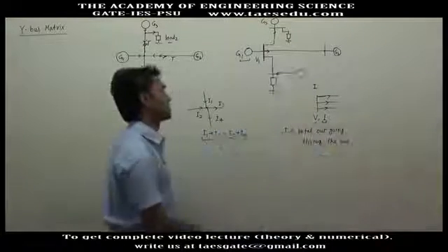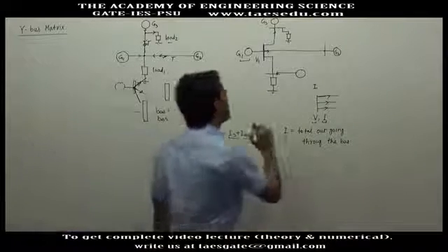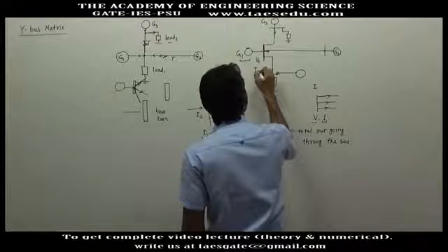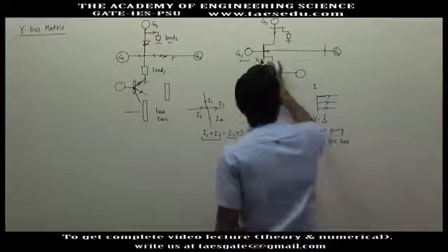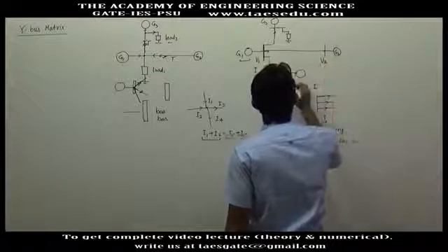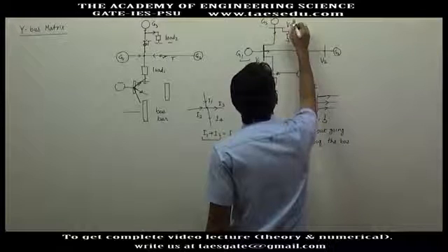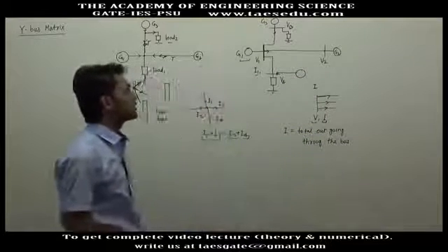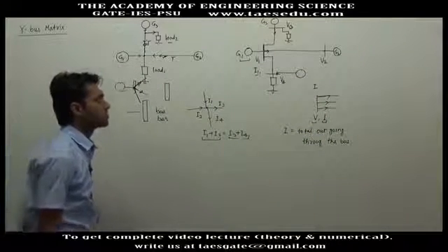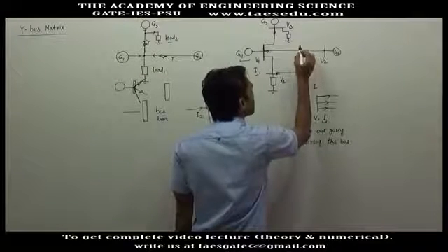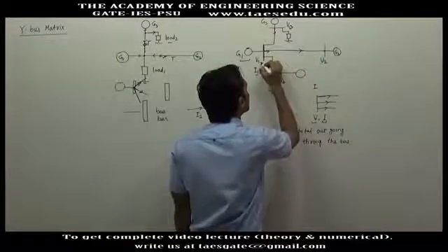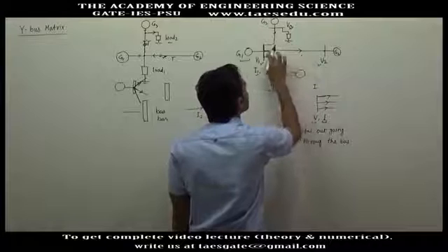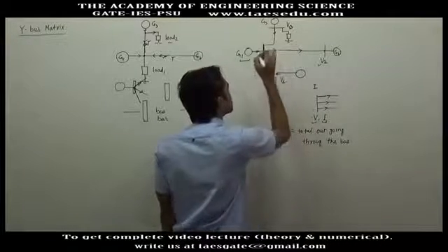Okay, this will be the current of a bus. So this current through any bus, let's say this is bus 1, I will define it as I1. So I1 will depend on V1, the voltage of bus 1, V2, V3 and V4. In general, this will be a function of all the bus voltages, because in this line the amount of current flowing will depend upon V1 and V2, and this current constitutes part of the current of bus 1.